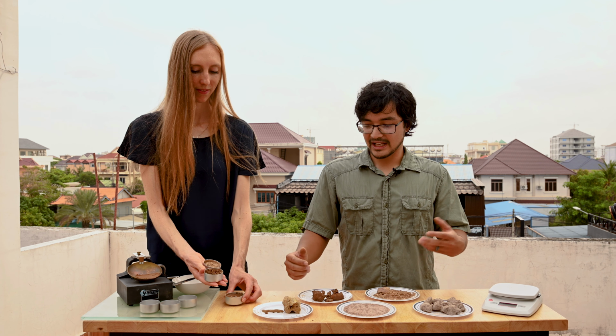For coarse-grained soils, you can also note the angularity and shape of the grains if they're large enough and significant. Angularity describes the roundness or angularity of a particle. If a particle is spherical and very rounded on the edges, it's good to note maybe it had been in a stream or some type of body of water that smoothed out all of its rough edges. Also, for shape, some soils are very flat or elongated, and those are good things to also note.